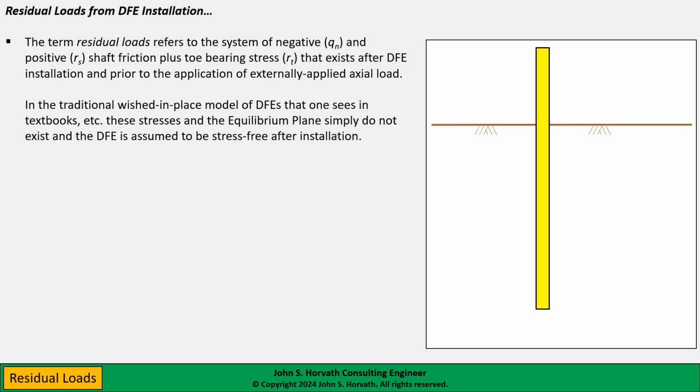And I do want to point out that although I'm talking about the geotechnical aspects here, we'll see that this wished-in-place stress-free assumption has some very, very significant ramifications for the structural design of at least certain DFEs as well. So this stress-free assumption applies to both the geotechnical and structural aspects of DFE design.